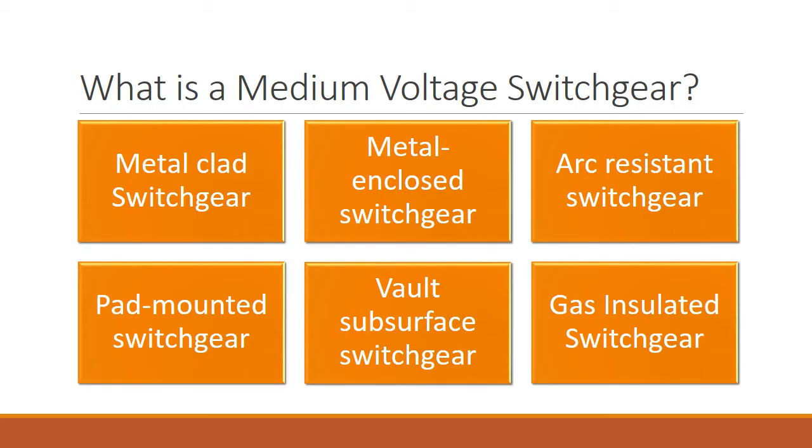Now, the last type of switchgear that I want to talk about is the gas-insulated switchgear, or usually what we refer to as GIS in short. These types of switchgear have sealed enclosures filled with insulating gas, which is often sulfur hexafluoride or SF6, or a combination of SF6 and other recently released insulating gases. The gas-filled sealed container allows for low-profile, compact installation. So it is actually good when space is an issue for your design.